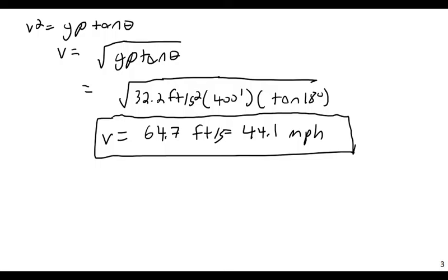In reality, we left out friction to make the analysis a lot simpler, but in reality, that friction is going to be quite substantial. If you think about it though, what this does is make it a lot easier for a car to go around a curve. And your tires have finite frictional capacity, don't they? They can only carry so much frictional force. And it's actually based on your weight.